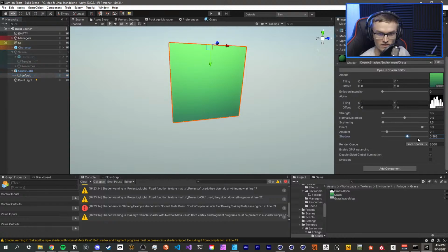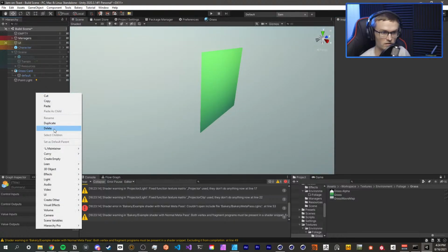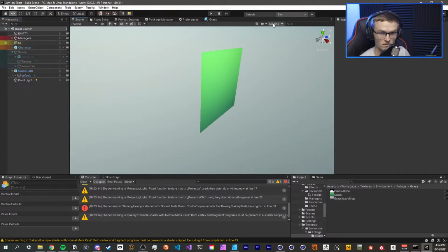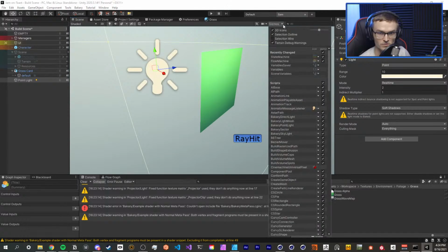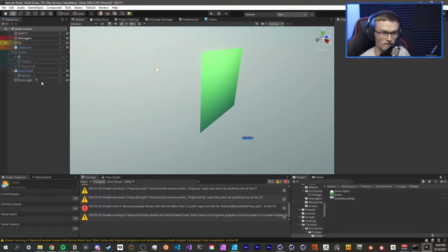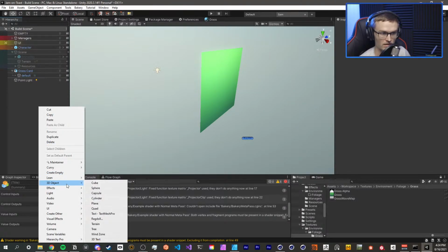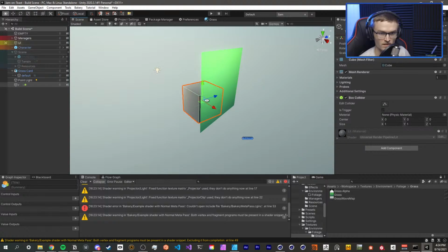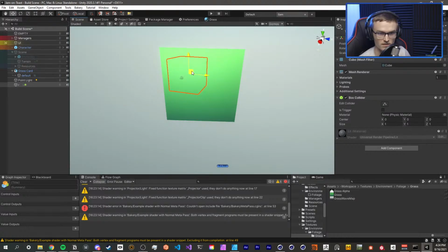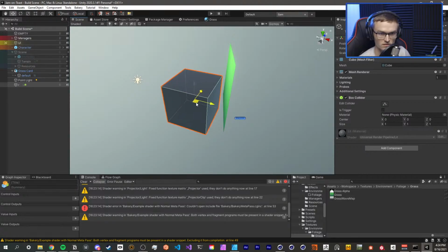Ambient lighting effect. Let's see how much shadow affects it. To do that, we're gonna need another object in here. Let's turn gizmos on so we can see them. I want gizmos on, but I want them smaller. I hate giant 3D icons. Okay. And then let's add another 3D object, like a cube. Should just go to that guy. Okay. And then we're gonna set this up right here to be in front of it.